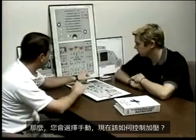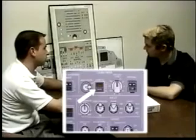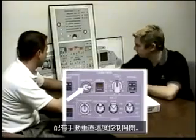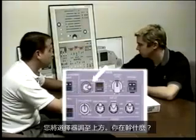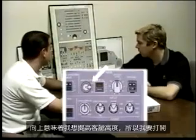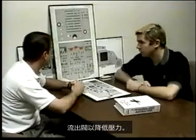You have a fault light on the mode select switch. What's happened here? That indicates that System 1 and System 2 auto pressure control has failed. Okay, so you select manual, and now how do you control pressurization? With the manual vertical speed control switch. You take the selector to up. What are you doing? Up means I want to raise the cabin altitude, so I'm going to open the outflow valve to decrease pressure.